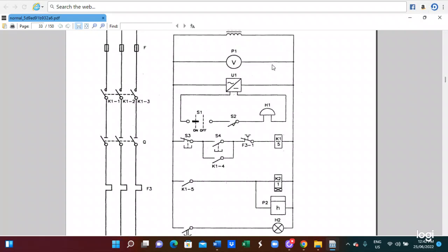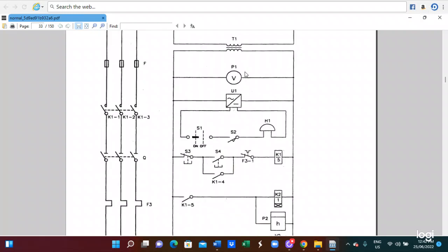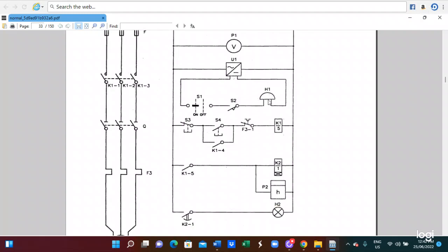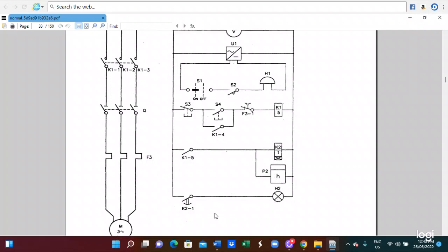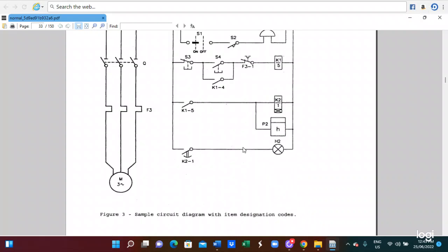The motor control circuit, this is the power circuit, this is the control circuit. Control circuits are controlled by the DC supply system. So the appropriate switch, those K1, K11, K12, K13 are controlled by the K1's holding coil, and those switch are the start and stop switch, and this is auxiliary contact. In the meantime, we can also see the timer. The timer switch is the K2 timer switch. In the meantime, this timer signal lights are also you can see. So this is for the connection of the motor control as well as the timer switch. Simplified diagram.